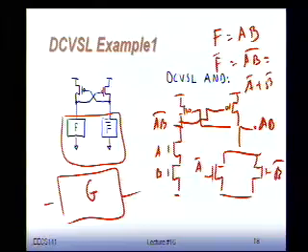So people have shown that if you take a fairly complex ALU, you look at how many gates you have to put in sequence between input and output to get the function, and then you do the differential implementation, you see that the differential implementation typically has about 50, 60, 70% less logic depth. Because you don't have to have these extra inversions, your logic is easier to implement.